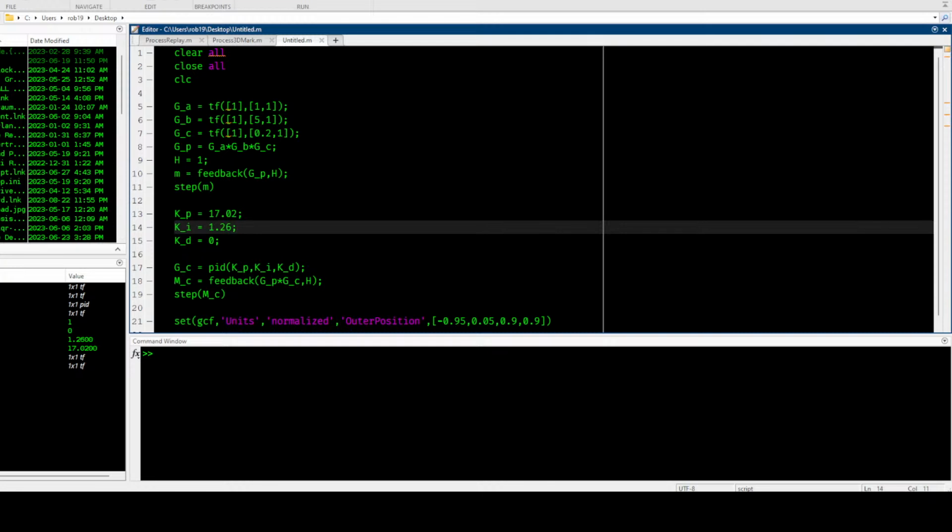Do me a favor. Look up Ziegler-Nichols. That's the Ziegler-Nichols method, which is what we were just looking at. That's the most popular way of tuning a PID controller. But the key point is no dead time. Systems with dead time, which will respond eventually, are a pain in the ass to control with PIDs.